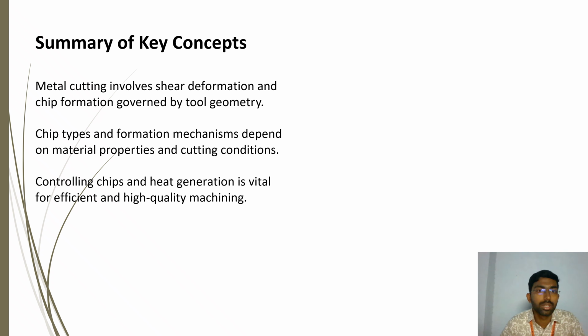Summary of key concepts. Metal cutting involves shear deformation and chip formation governed by tool geometry. Chip types and formation mechanics depend on material properties and cutting conditions. Controlling chips and heat generation is vital for efficient and high quality machining.